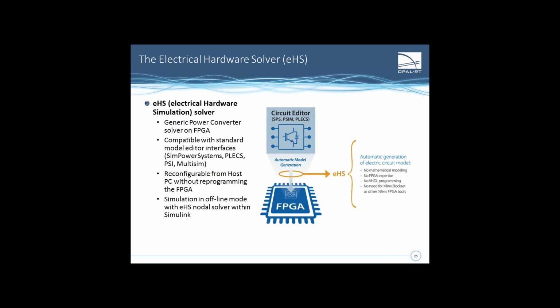The idea is that the circuit is designed with a generic circuit editor, for example SimPowerSystems, PSIM, or Plexim, and the actual matrices that are solved for the simulation are automatically generated and loaded onto the FPGA at the start of the simulation. So you don't need to know any VHDL, you don't need any FPGA expertise to use it. It's really easy, and you can use it out of the box.